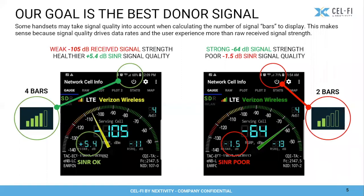If you take a look at the left side picture, this is showing 4 out of 5 bars. Now this is actually not a super strong signal. It's -105 RSRP, but the signal to noise ratio is not bad. It's +5.4 dB. And yet, even though it's a low signal level, you're showing a lot of bars on this, quote, customer's phone.